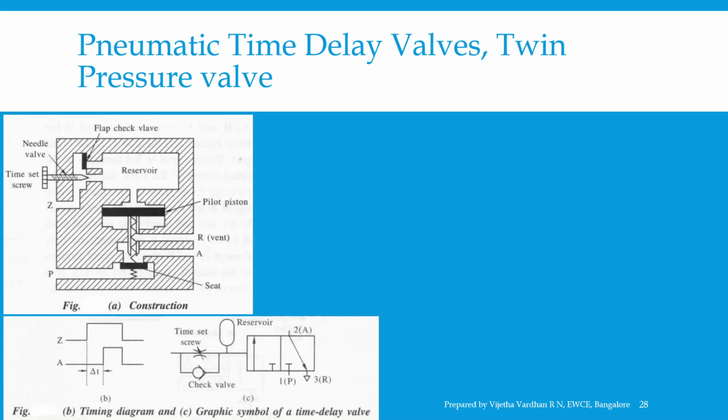The valve shown in this figure is a normally closed delay on valve. Many other time delay valves can also be obtained. All of these use the basic principle of the air reservoir and the needle valve.